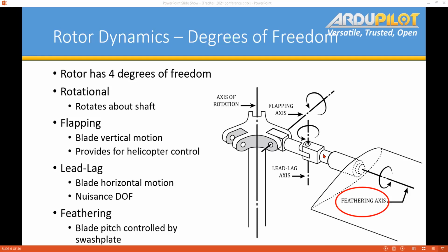You can use the blade pitch to make collective blade pitch inputs, so all the blades either pitch up or pitch down at the same time at every point around the azimuth, or you can make cyclic blade pitch inputs, where one blade will change its blade pitch in a cyclic motion so that it creates more longitudinal type forces than lateral. So that's the idea behind the cyclic blade pitch, and the idea for the swashplate is to provide that cyclic blade pitch motion.